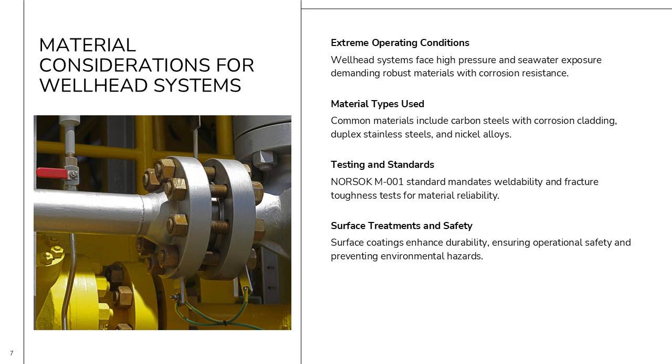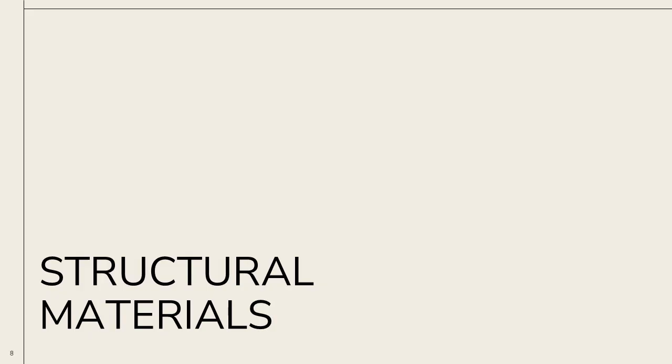NORSOK M-001 recommends rigorous testing for weldability and fracture toughness. Surface treatments and coatings may also be applied to enhance durability. The choice of material impacts operational safety and reliability, as failure in these components can lead to catastrophic blowouts or environmental hazards. Selection of structural materials for offshore platforms.